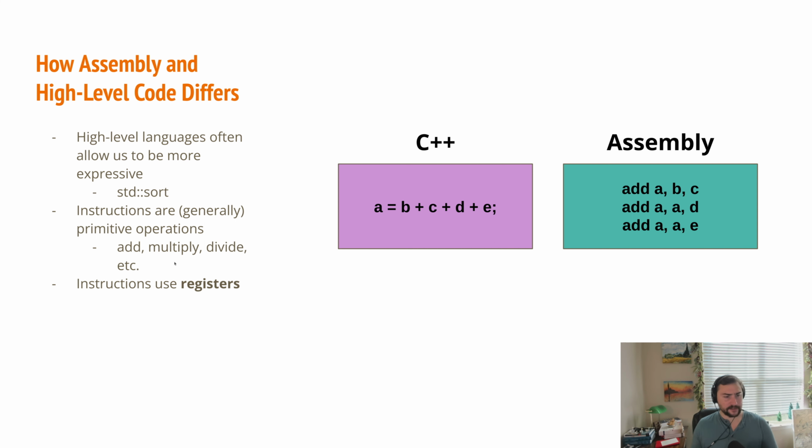Likewise, we have to be somewhat cautious in terms of how specific we're going to be with the instructions that we implement. At the end of the day, that's going to take up some silicon on our processor, and we have to make sure that the programs that are going to be running on our processor actually have a use for that instruction, right? If we implement an instruction that's never used, it's kind of pointless.